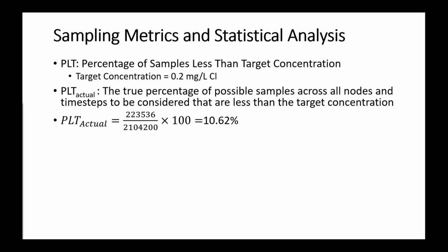For example, for the BWSN Battle of the Water Sensor Networks, the denominator, the bottom half of the equation, looks across every single point in the network, across every time step that we have measurable; we use hourly time steps.